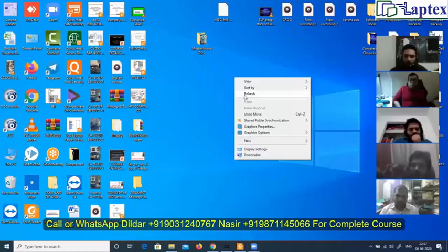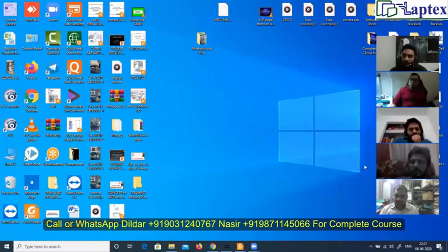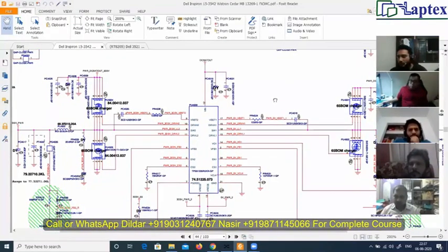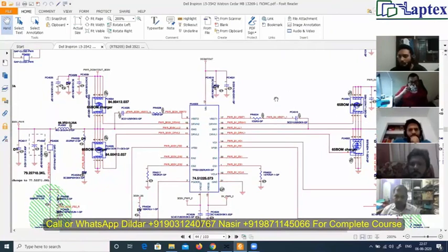To enable the 3 volt, 5 volt section, right? So did you check that, Joe? I told you to check the schematic and the board. What was the voltage coming at the entry 1 and entry 2? I think I told you to check, about 1.35 volt should be coming there. Did you check that? Yes, sir.